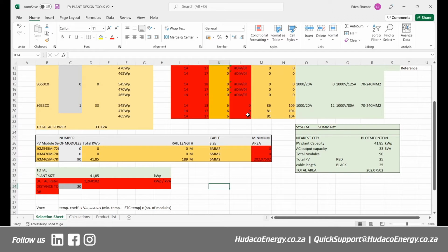And the string length is 15. So with time, you would know that what is ideal for a 33CX, if I'm working with 465 panels, is 15 panels per string. As you become more and more used to your designs, it will become very, very easy, right?